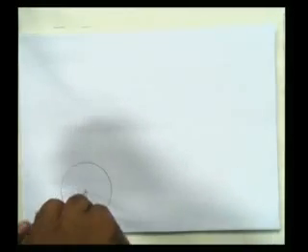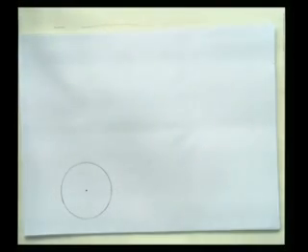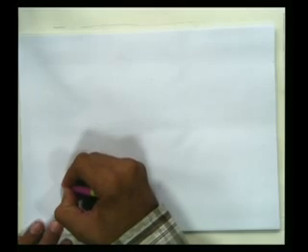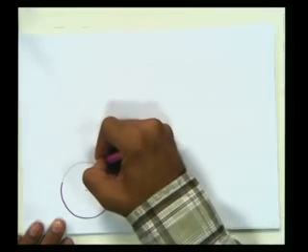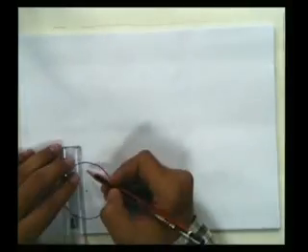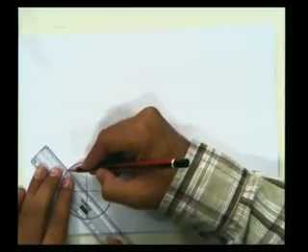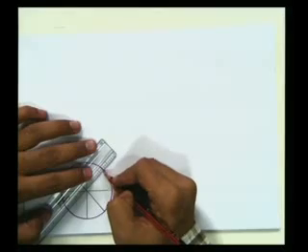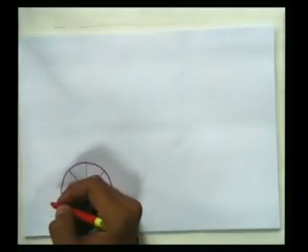So here I go. This is the base circle, this is the center of it, and it is a cone, so the inner lines won't be visible to me. So just the base circle, I'll make it dark. I will divide this circle into 8 parts as I always do, and you should use the arc method or your protractor to cut the circle into 8 parts. I'm doing this quickly so that the problem is completed. It gives you a good insight of what the problem basically is.